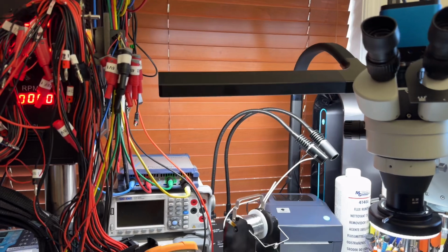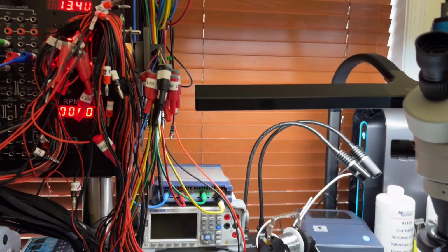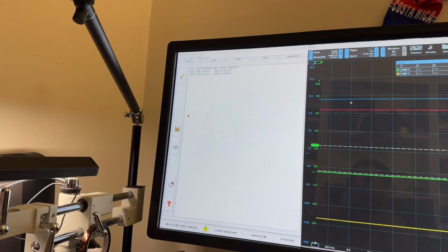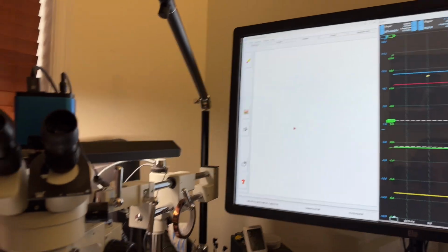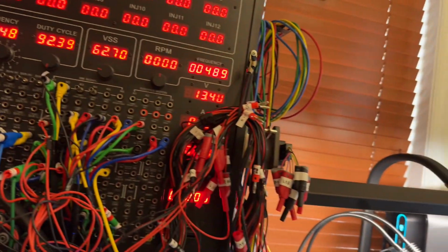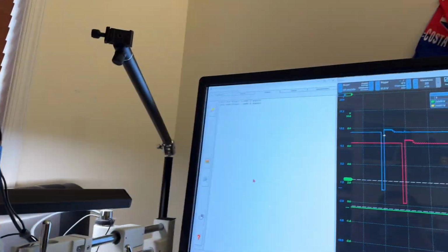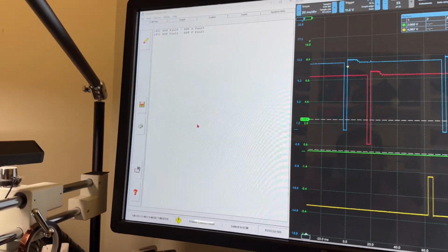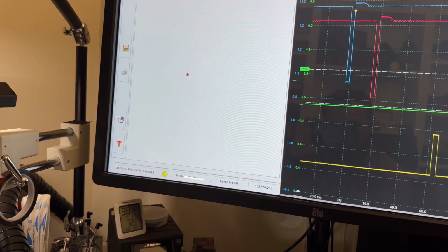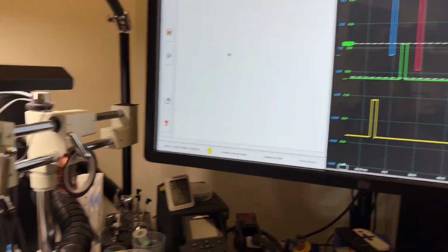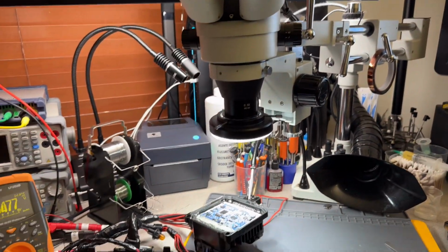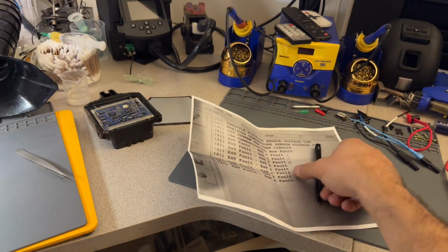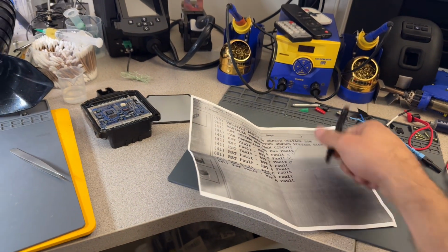I'm going to unplug this one here, plug this one here, erase the faults, and run the computer again. And we now have G and F. So now we got F, that is the other fault that we set up. So H is gone. So now H we know is good, right?